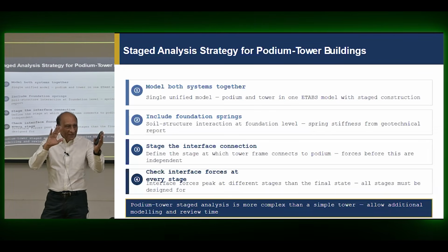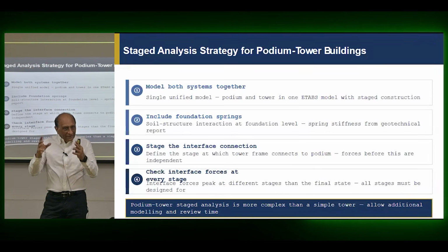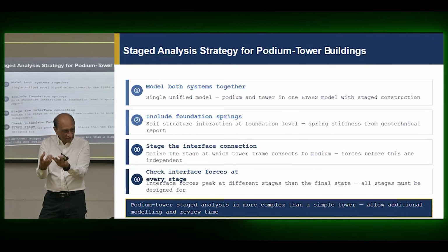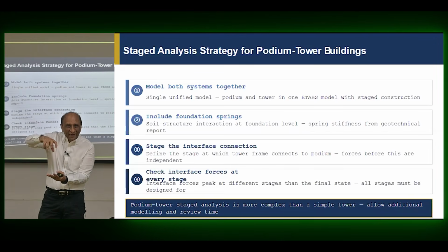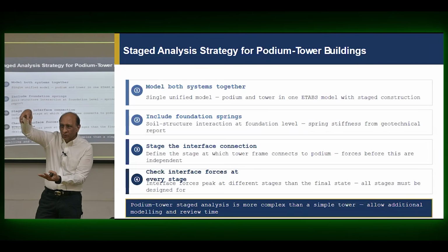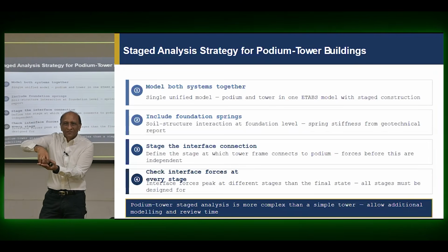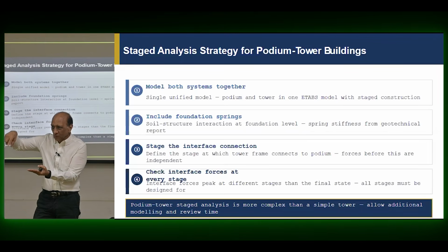And then do all the analysis for lateral and whatever else you want to do, and then you can get those forces, right? Then create a model of the podium and apply the forces you obtained from each tower, because you take the podium to be the foundation. So you just transfer those forces from each one of them.